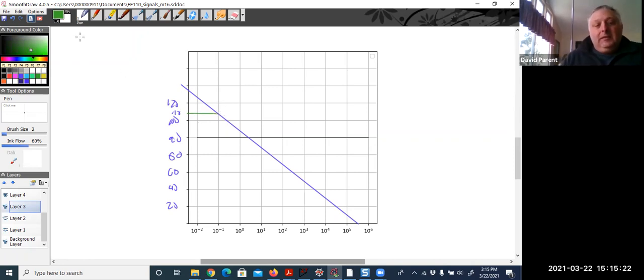So really, you're given this value and you're given this. Normally you would be given some number, we'll just say A over s plus B, where that's the break frequency. No, you're given this point here, not this point here. So you just draw them asymptotically towards each other, and you can back calculate what B was.